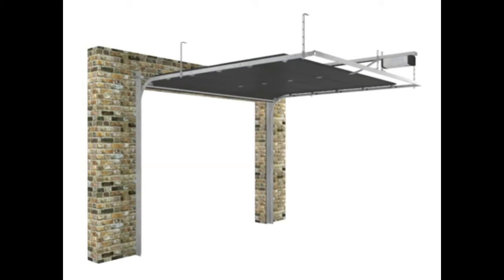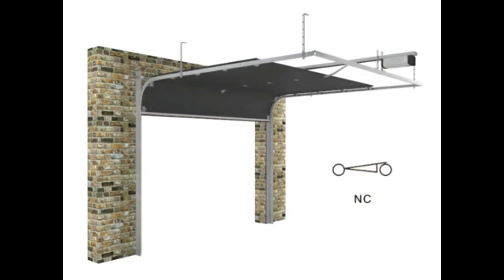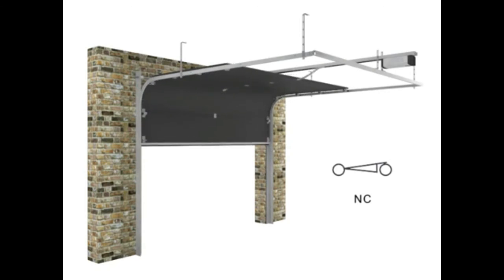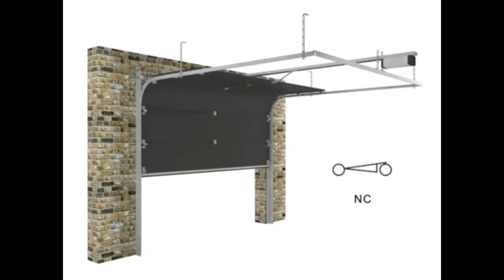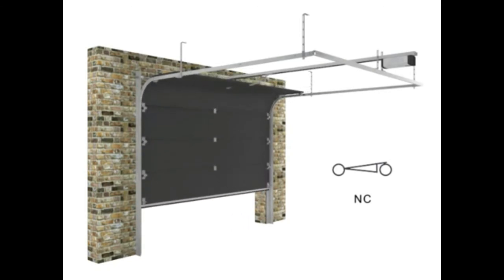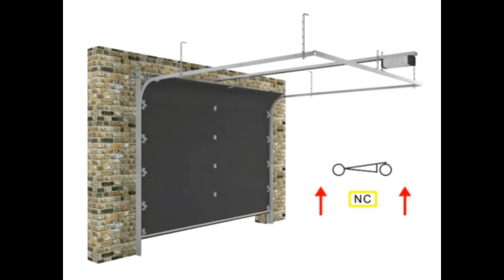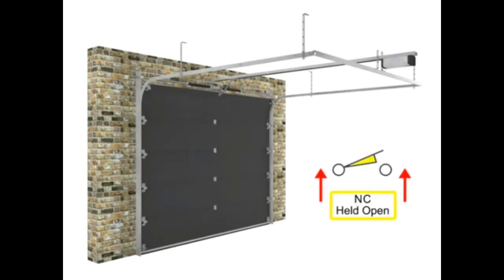A garage door circuit includes a limit switch that will remain closed until the actuator comes into contact with the floor. When the garage door motor is activated, it will continue to close the door until the lower edge of the door hits the floor. When opposing pressure is applied to the normally closed limit switch, current to the motor is interrupted, stopping the motor and bringing the door to rest in a down position. In this way, the limit switch defines the limit of movement of an object.